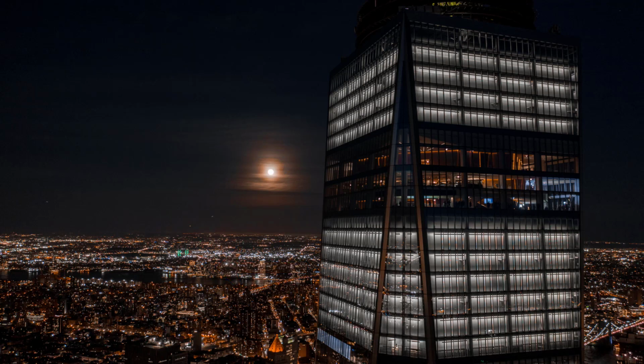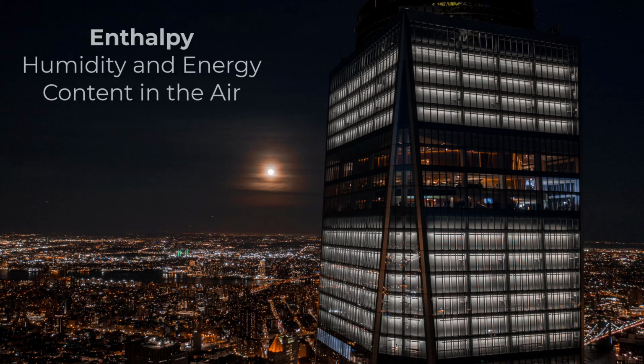Larger buildings having significant investment in BAS controls might consider enthalpy, a measure of humidity and energy content in the air, to establish the most energy efficient HVAC system sequence of operation and optimum start. However, this should be closely reviewed so that it is proven to be an effective energy reduction strategy.